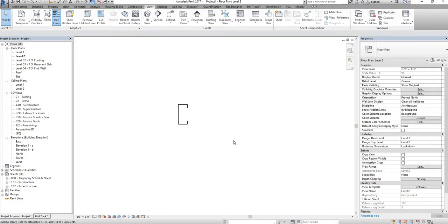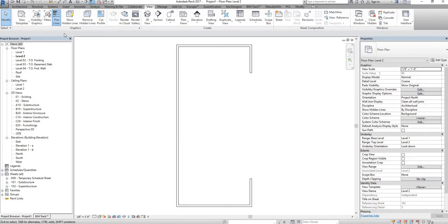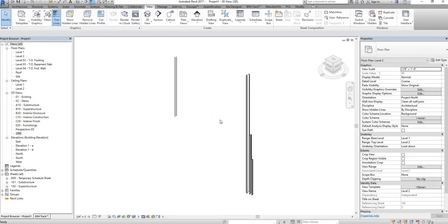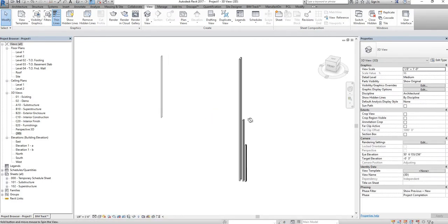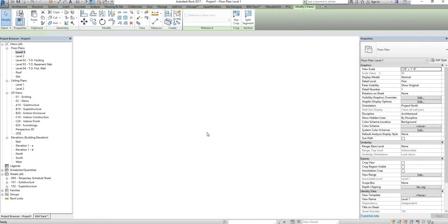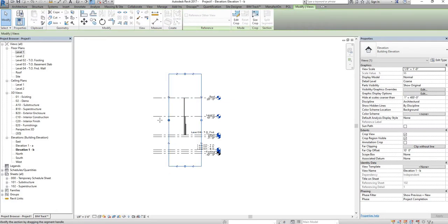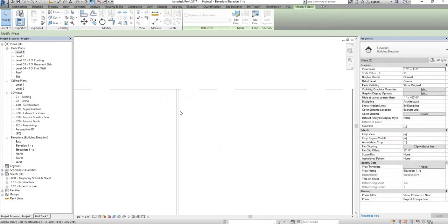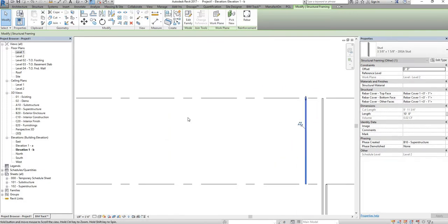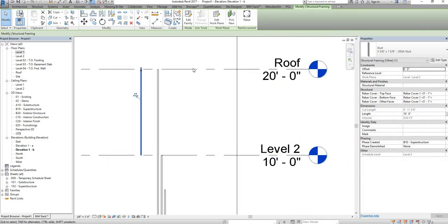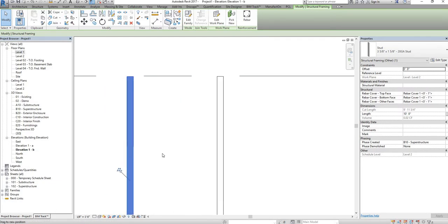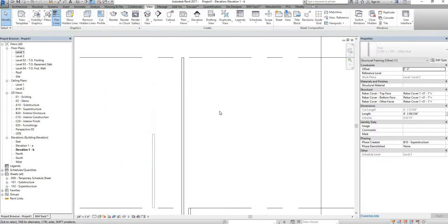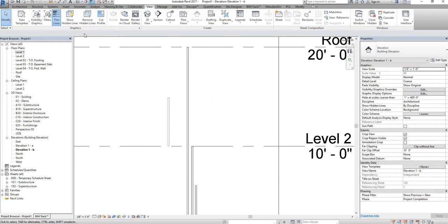It's kind of silly. I don't understand why I did that. Anyways, you can see there, it attached to level 2 and then it went up 1 level. If you wanted to detach it, bring it to here. It also attaches to work planes as well.